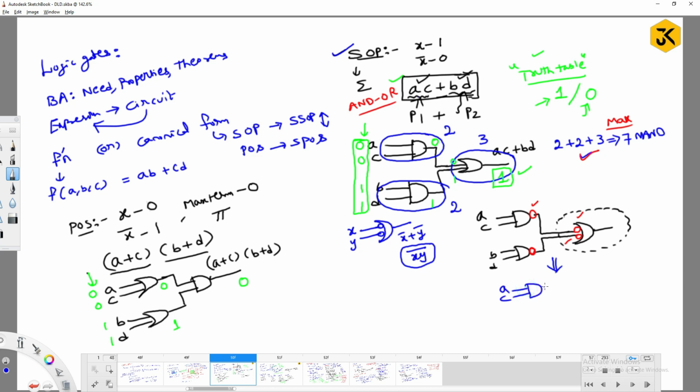The same structure I will redraw like this: (AC) complement and (BD) complement, and I will redraw it in terms of this dotted notation representation as, observe, (xy) complement, which is again one NAND gate. You are going to get again AC plus BD, right?